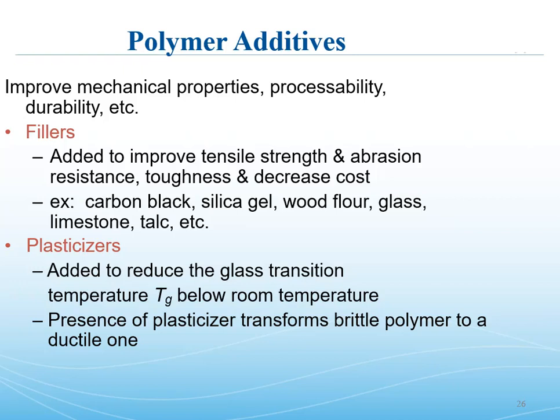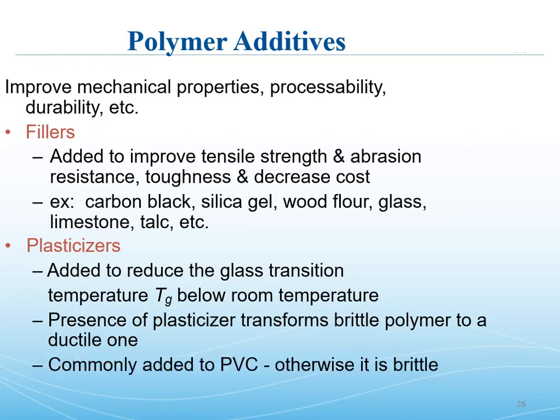The caveat there is if the plasticizer migrates back out, which they tend to do, they are not thermodynamically necessarily happy in the polymer matrix. They will tend to bloom to the surface and form their own phase, and then of course the polymer gets brittle. So something important to remember.